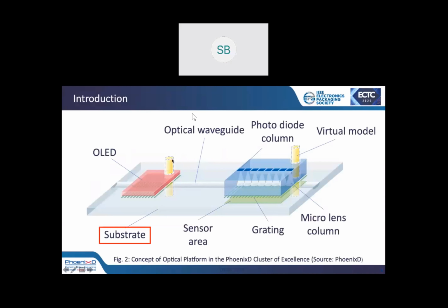If we look at the concept of the waveguides in further detail, we can see on the right side the process flow, with the pre-structured PEEK substrate and a sidewall coating using PVD processes. The sidewall coating will be the cladding of our waveguide in this case. The material chosen is a gold layer. The cavity will be filled using doctor blade or spin coating processes with PMMA, and if desired, a top coating of gold can be applied onto the waveguide material.